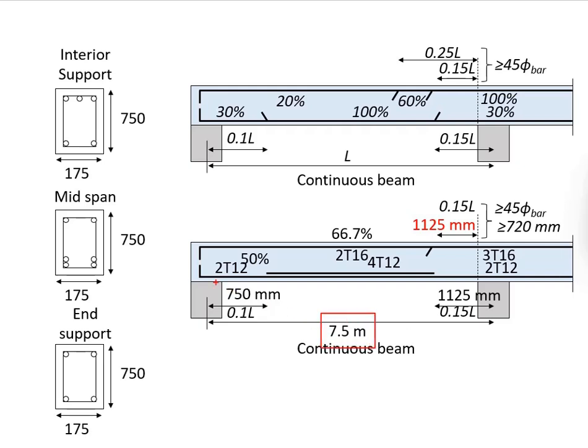7.5 meter, the 10% will be equal to 750 mm. Make sure you round up to the nearest 25 mm. This is due to the considerations of the construction site, where the workers measure the dimensions using imperial units. 25 mm is equivalent to 1 inch. This allows easy conversions between the SI units and the imperial units.